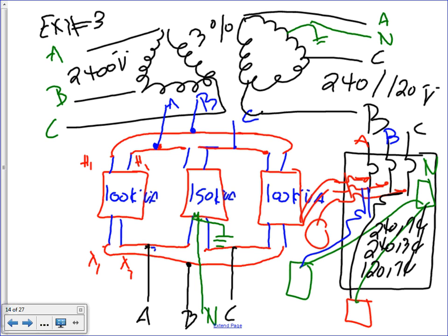Now, good point, could I have used 208? Now I have 3 voltages. If you use it, would it run? It will. It will burn your transformer. It will unbalance your transformer. If you have a smaller load at 208, could I have run it? Yeah, it will unbalance the windings. Certain windings will be overloaded. Let's just keep moving here. Could I have run it with certain loads and calculate it? Yes, but you're not supposed to, based on the code.